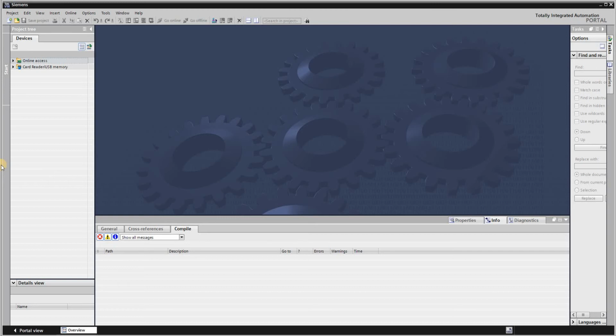So let us assume a project where we have 10 IOs or 15 IOs. The first thing we need to understand is what components we need for our system. If it is a 20 IO system, what are the components? Like if you have 5 AI, 10 to 15 DIDOs, any stuff. So first we will make a hardware structure.